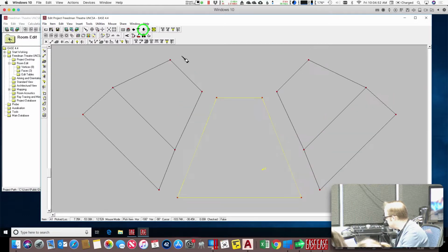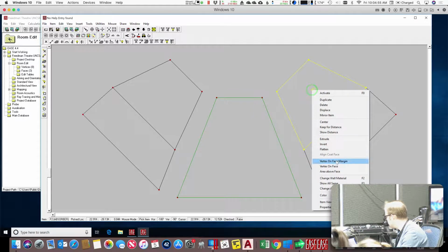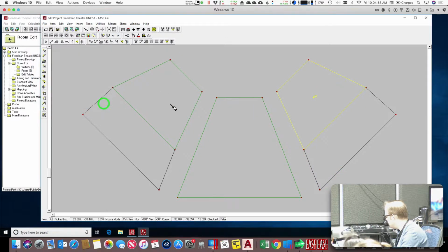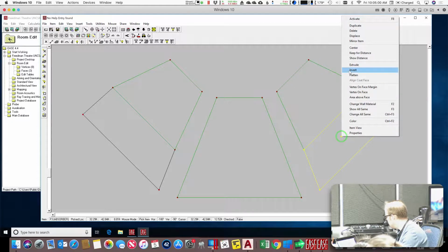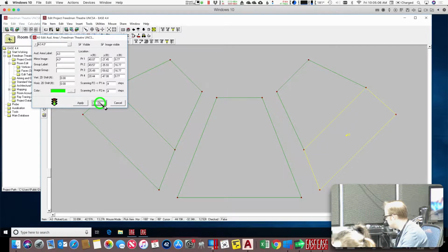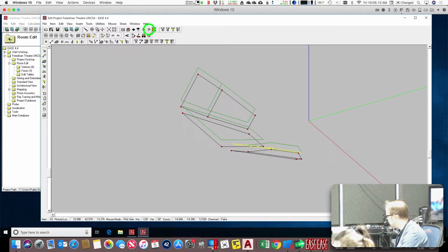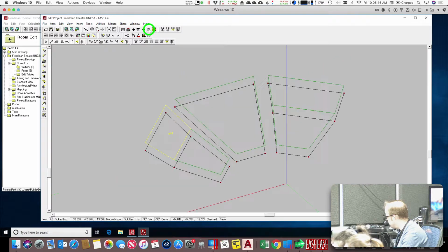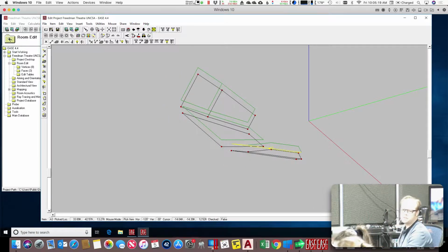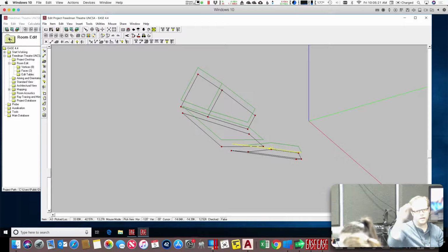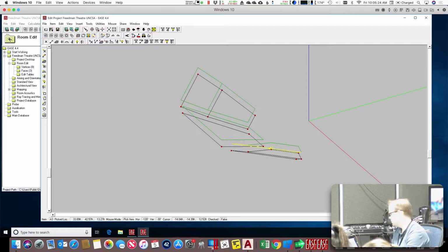So what you ought to do is repeat that process for every one of your surfaces. Now, because we're still in mirrored mode, if you do it for one of your sides, it should replicate it on the other side as well. So now, if I look here, I've got little audience areas hovering above my surfaces, at the height where the ears usually are. Those audience areas are where we'll be able to plot sound.